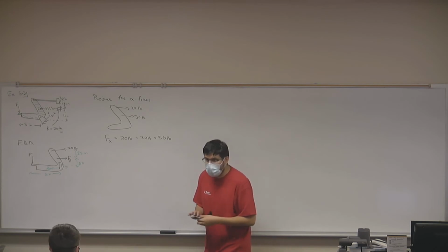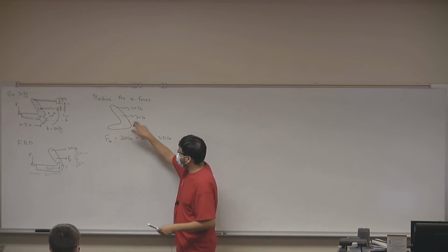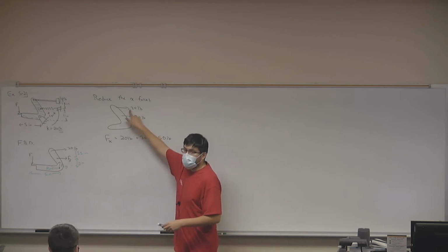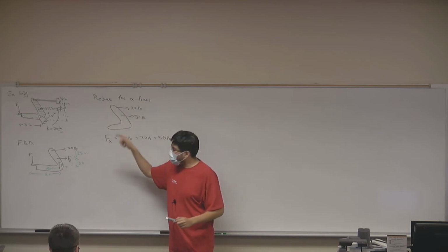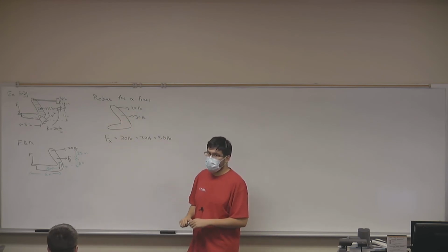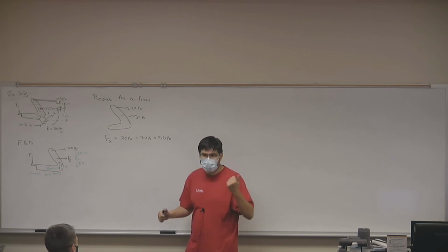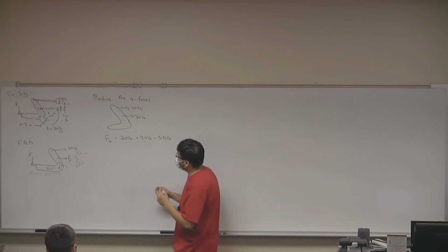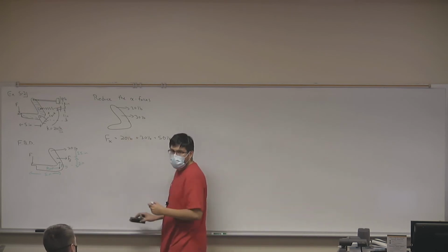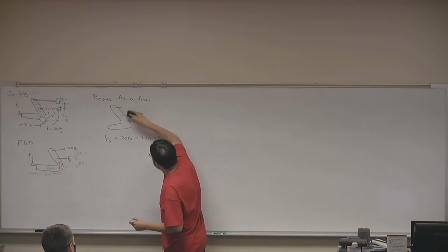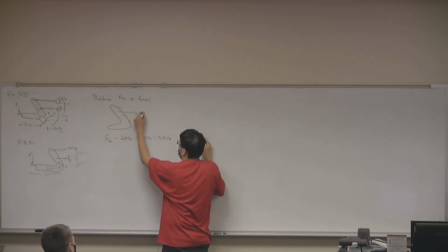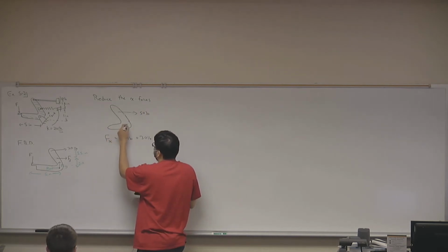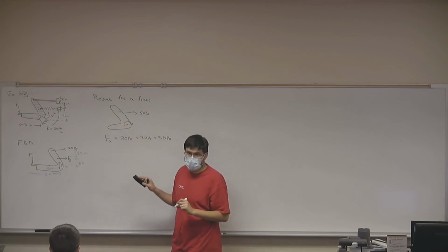If it kind of rings a bell, remember, this is what we call the net force, just the sum of all the forces. If this were a 20-pound force towards the left, what would this reduced force equal? That would reduce down to 10 pounds. Exactly. Okay, so you're adding the magnitudes up, considering the direction. However, I need to figure out where in the system I am going to place this force. So I have a 50-pound force, but the question is, where do I put this force? I need to put this force wherever it causes the same moment about the hinge as the other two forces